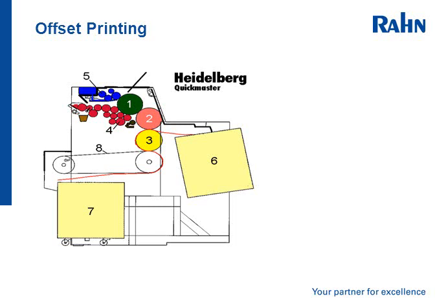The basic aim is to provide ink in a thin film to a litho plate, which also has applied a fount solution. These products interact. The fount solution, or water-based material, causes the non-image area to stay clean, and the ink coats the printing area.